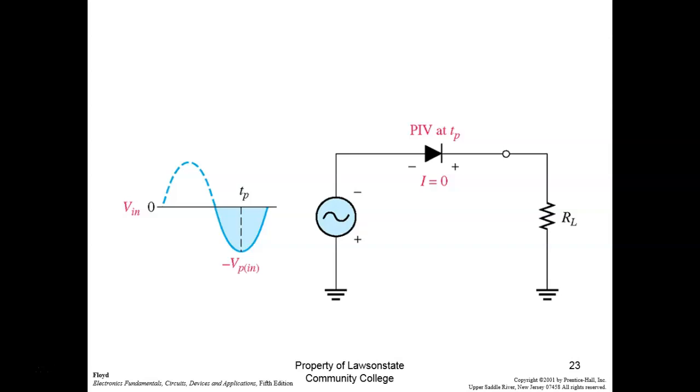If you buy a transformer, what voltage is this transformer going to be rated? Peak, peak to peak, or RMS? No, it's RMS. So this is a 12.6 volt transformer. They're rated in RMS. Why RMS? Because that's how much work they'll do into a resistive load, right? But what I have to do is figure out what the peak voltage would be out of that transformer, because that's what's going to bop my diode, right? Does that make sense? And how do we solve for peak if we know RMS?